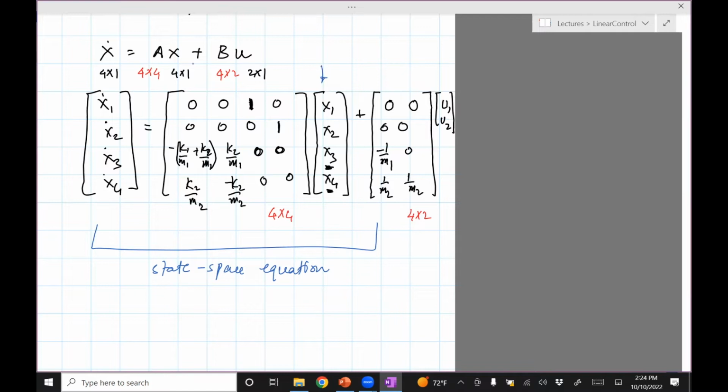When you integrate this, you'll probably use some kind of numerical method, which means that you take x dot and expand it, like, let's say Euler's method, as x at time t plus delta t minus x of t, divided by delta t, and then move things around. And so it'll tell you how x at t plus delta t is a function of x at t and u at t. And then you can keep doing that to get the system dynamics.